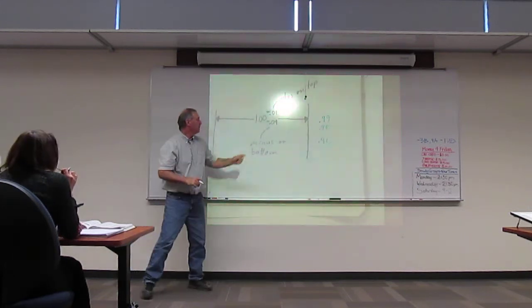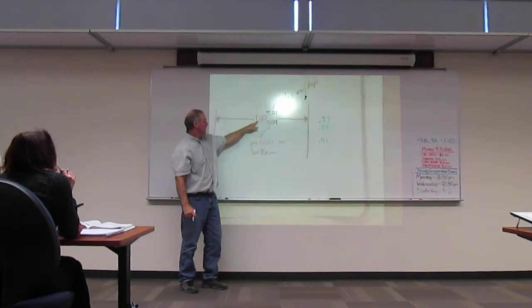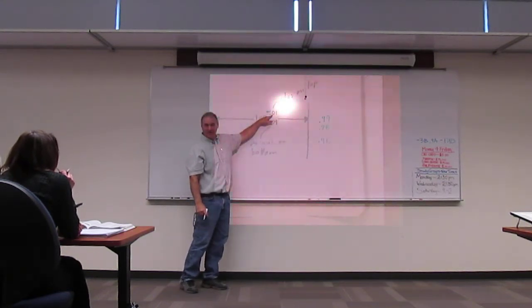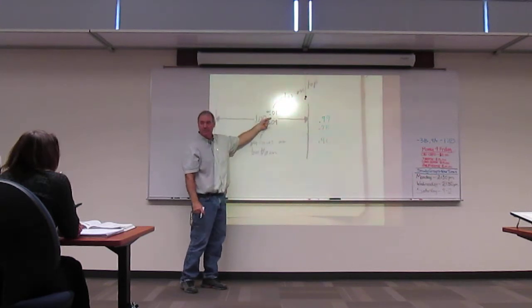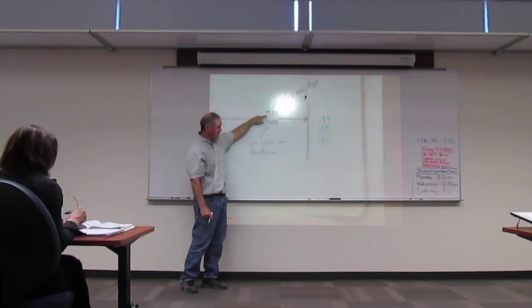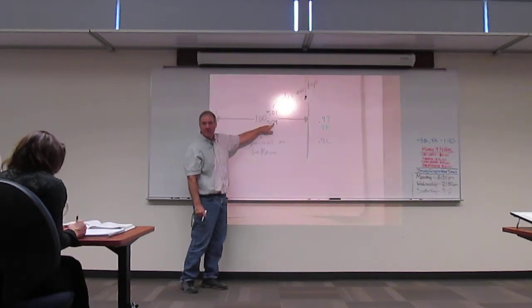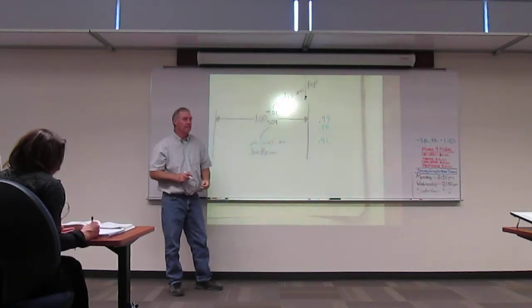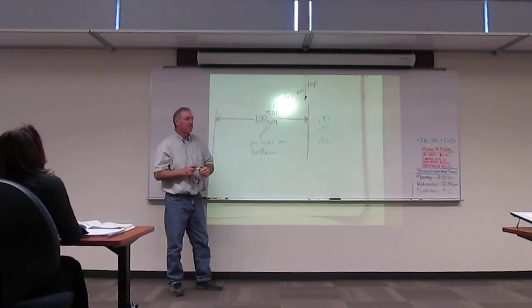Okay. I take my basic size, and then I apply my tolerance to it. So 1 minus 0.01, and if this was a plus, I would add it. So minus 0.01, minus 0.02, minus 0.03, minus 0.04. Okay. So I can get that whole gap there. Okay, so this is called lateral tolerance.